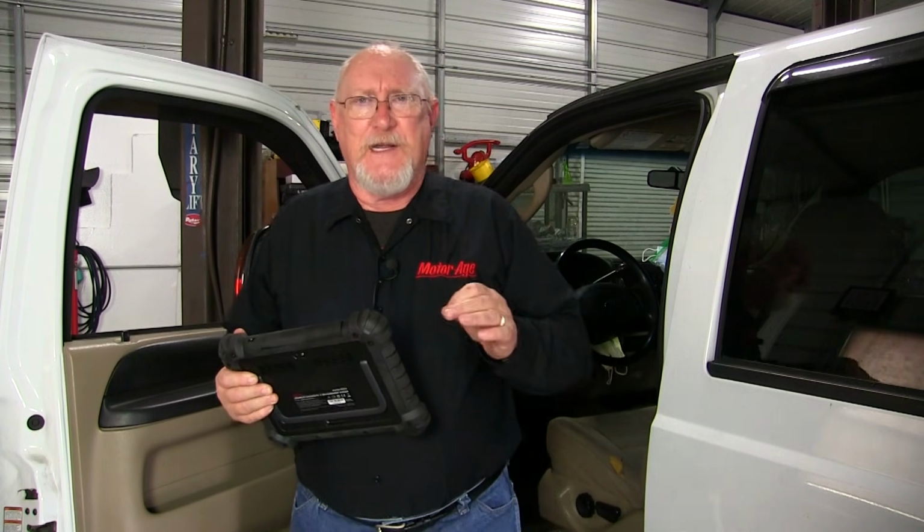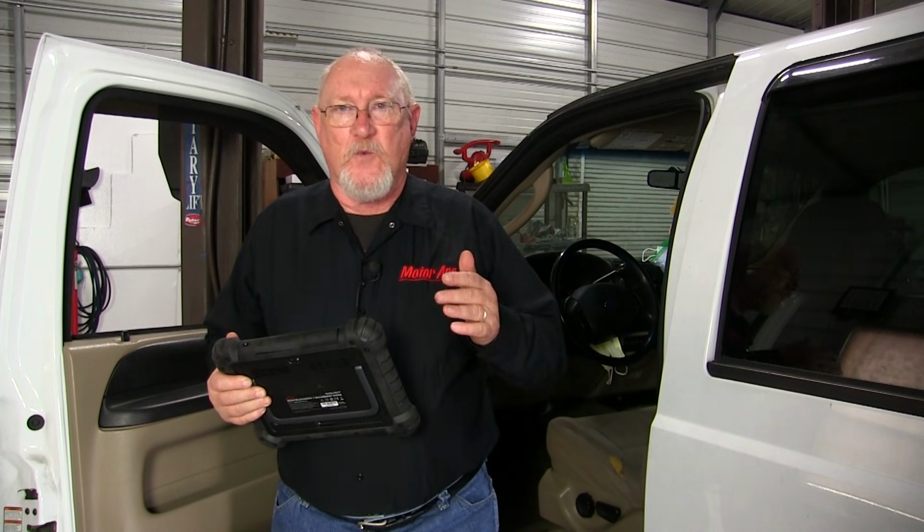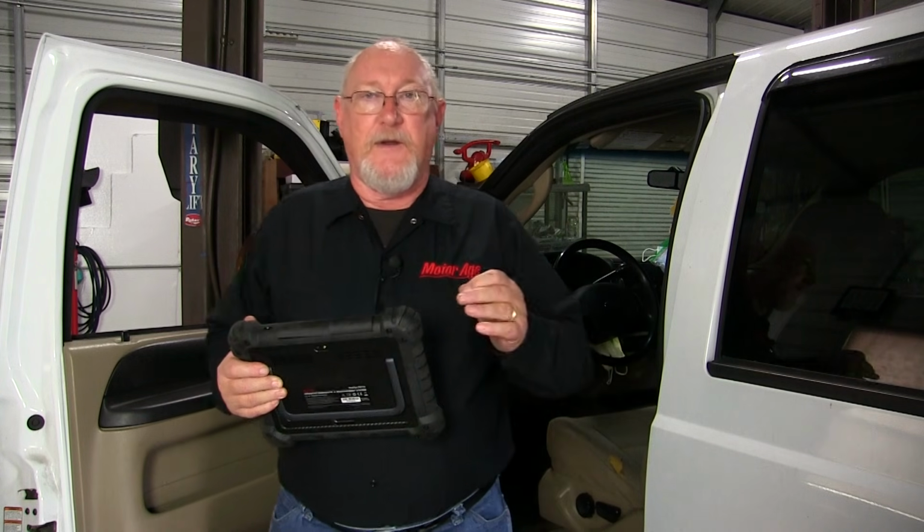There are a few things that we need to know before we even begin our troubleshooting. For example, just what networks are there on this vehicle and what modules belong to which network. Another thing I want to know is, do the networks pin out at the DLC, allowing me a direct communication with my scan tool, or do I have to get that through a gateway module? I also want to know, are there any networks on the vehicle that I can't communicate with? Now that I know what the code is, it's time to do some homework.